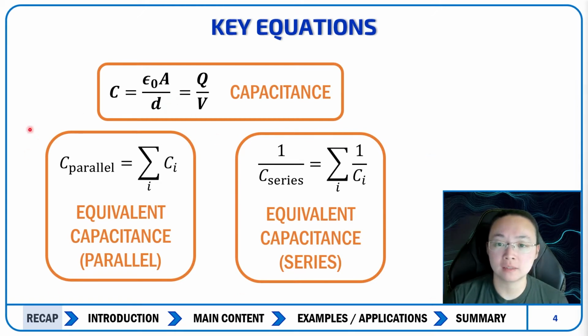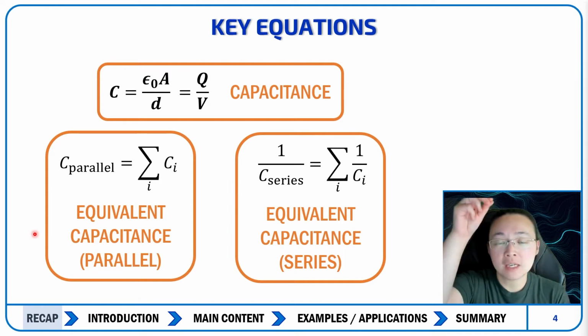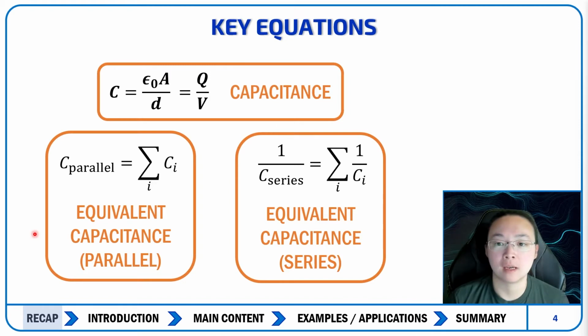One important concept to understand is the difference between putting capacitors together in parallel or in series, because when we talk about resistors, the trend will be reversed. So with capacitors, if you set them up in parallel, in which case you have the same wire being split into multiple parallel capacitors, and then also having the wire come back together at the end, so you have the same wire at the top and the bottom. That is a capacitance in parallel.